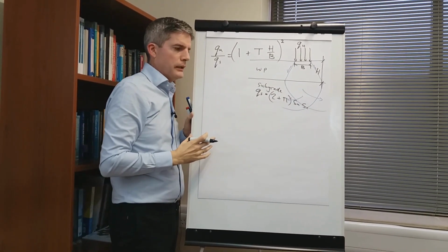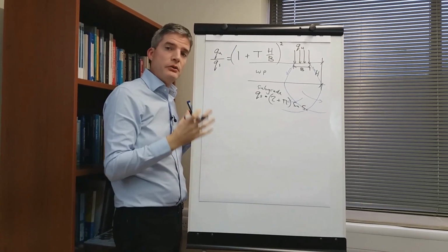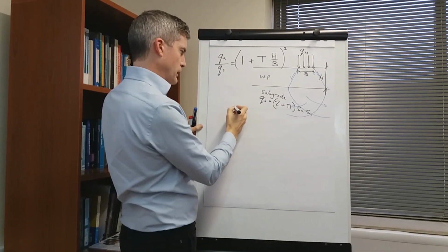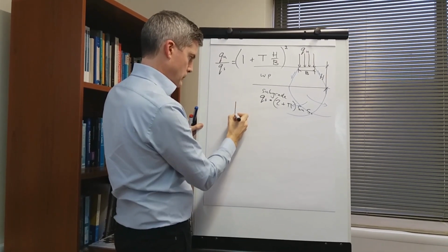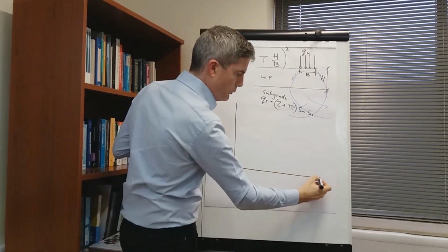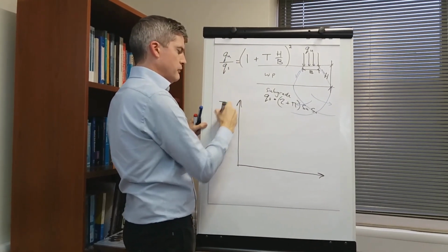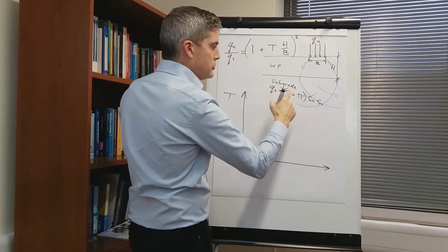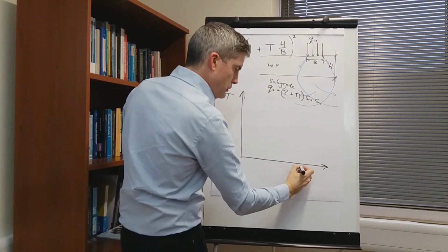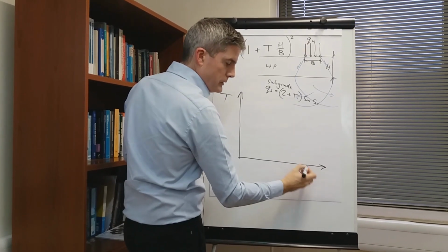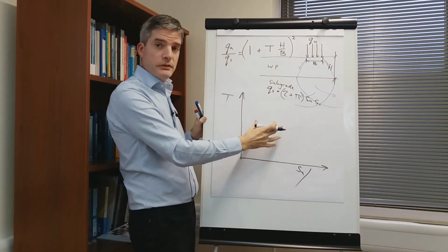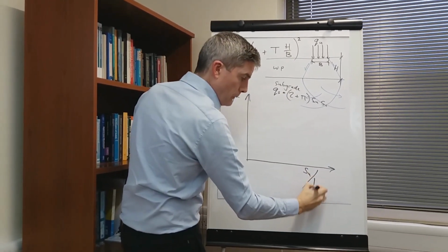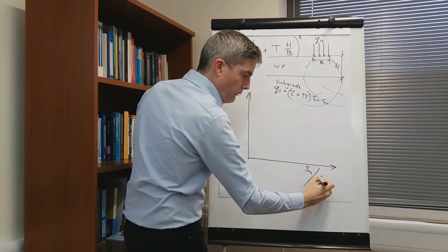By back analyzing a lot of physical testing and numerical analysis, we derived again quite a simple relationship for T. We need to find this value T. If we plot it against the strength of the subgrade, SU, normalized so it's dimensionless, so all the units cancel out in all these expressions, which is another big advantage of the method.